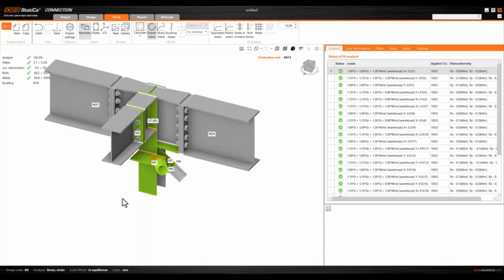And again, we have the results of the buckling analysis, where we have an amplification factor of 4.99, which is very low according to what we have discussed. Let's display the buckling shape first to understand where this buckling factor comes from.